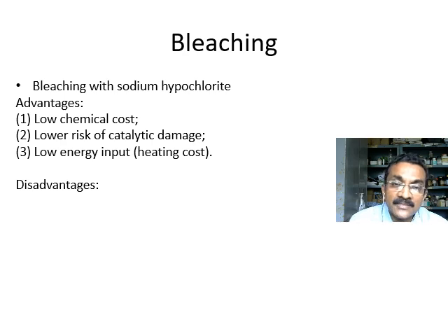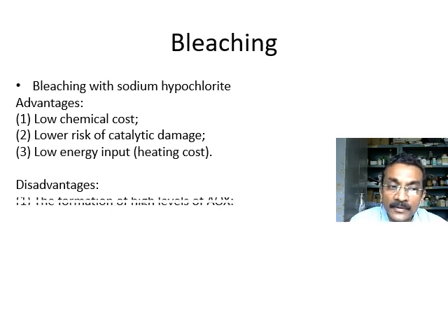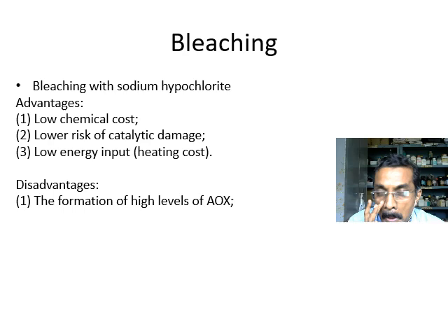At the same time, there are some disadvantages of sodium hypochlorite, and the major one is that sodium hypochlorite is non-eco-friendly in nature. So the AOX level, adsorbable organic halogens, is very high. These residual halogen compounds are responsible for the non-eco-friendly nature of the textile material.